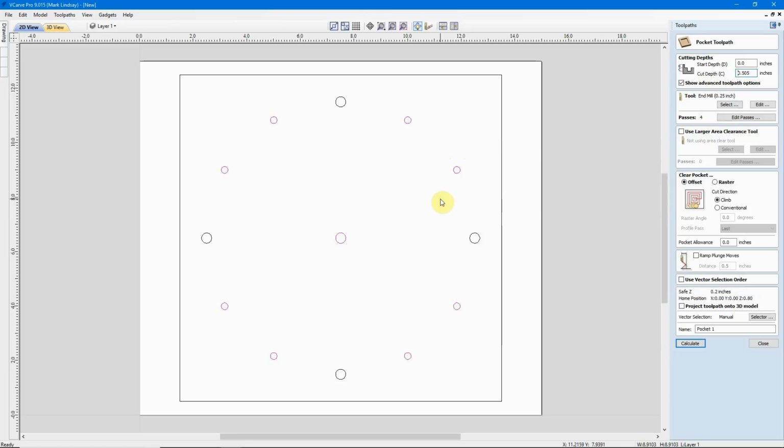I'm not talking anecdotally here. I'm speaking from experience. I don't know a fellow who did it. I did it. I started a fire on my CNC table, drilling straight down using a downcut bit, not knowing any better. Ruined the project, and I had to replace the spoil board. Do not drill straight down into a hole with a downcut bit. Use an upcut bit, always. Okay, enough with that soapbox.